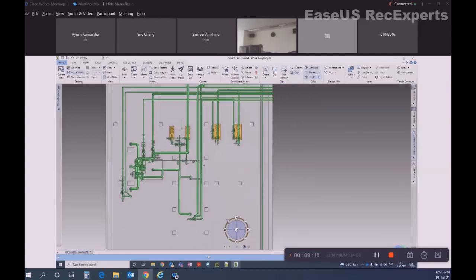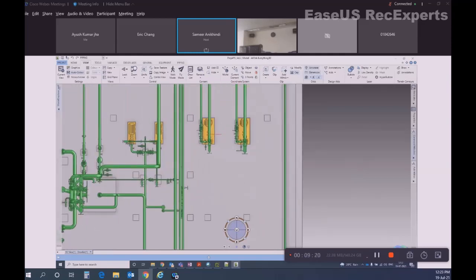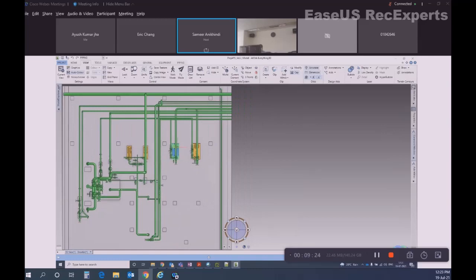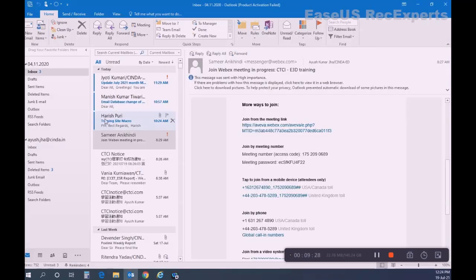Now there is a third thing called a local view. Local views are made for individual entities. Like for example, I want to make a local view of these two pumps. Select this, copy to a local view. So it forms a separate draw list. I want to analyze these two pumps separately. So draw list is separate for sure because draw list 2 is there.